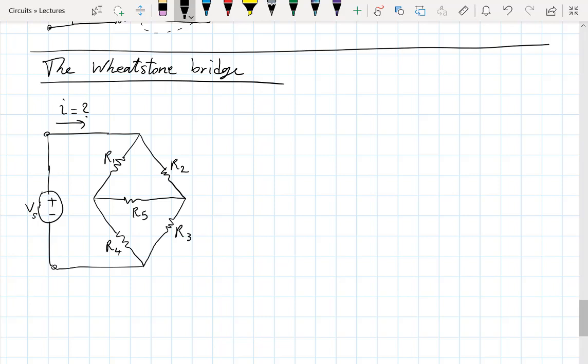Now, if you wanted to do that by using these techniques, the wye-delta transform will come in very handy here, right? Because you can take the top part, the delta there, convert it to a y. So it would look like this. And now, basically, I'll forget about R1, R2, and R5 in black.